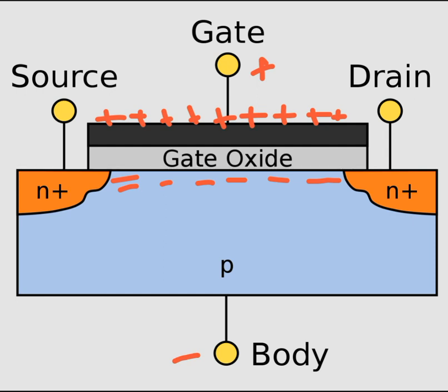Now what if, as opposed to the previous situation, we apply negative potential to the drain and the source is tied to the positive terminal? So in such case, what do you see? The current direction. Will there be a conduction? Yes, there is a conduction because the channel is inverted with lot many electrons, and n plus regions on either side of the transistor are with so many electrons already.